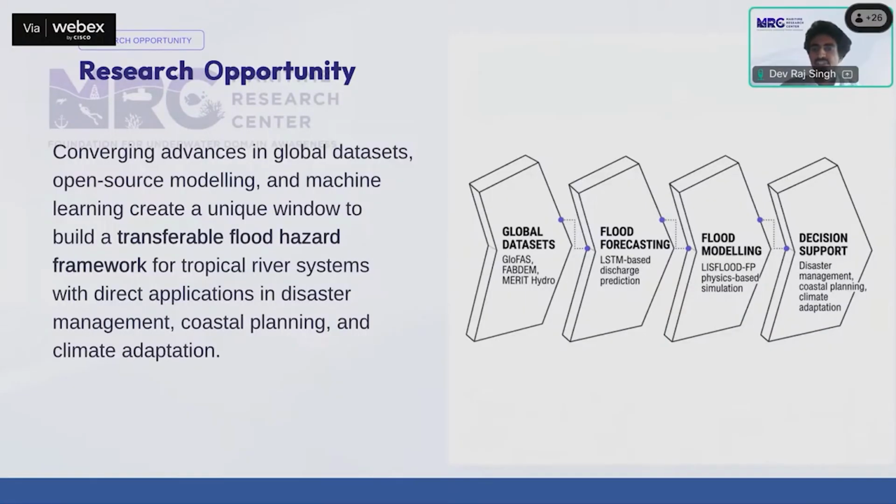First, we can go with the physics-based approach, for example LISFLOOD, in which we'll apply physics-based equations like inertial equations and computational fluid dynamics equations, discretized, that can help us model the flood simulation. The other one is the data-driven approach, where we'll use machine learning techniques to train on many deltas and then get our results.